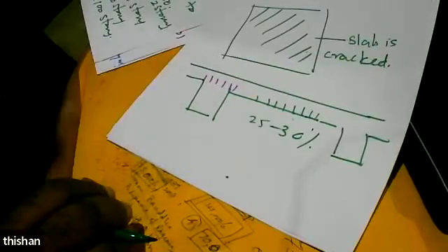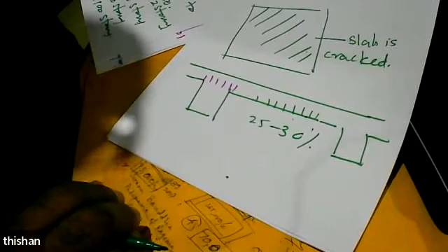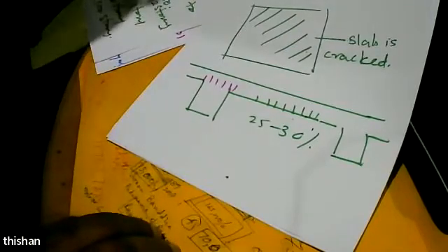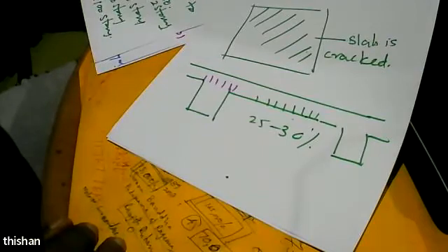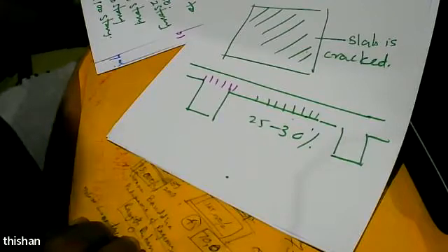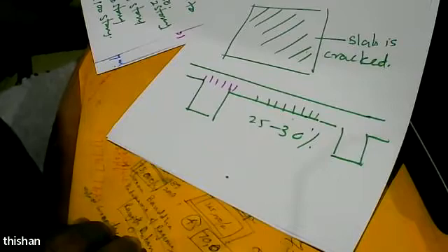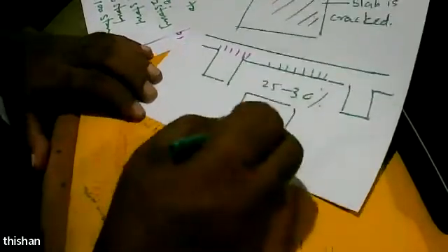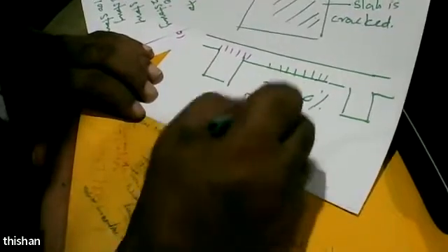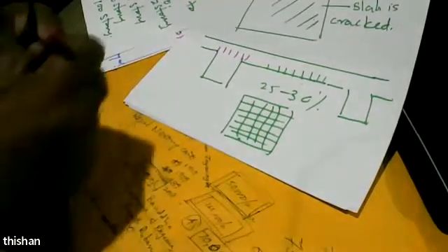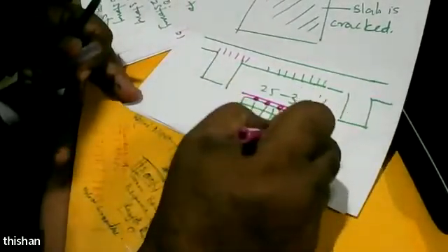So what you do is you go to set modifiers in the program and then adjust the stiffness of the panel that is used to represent the slab. So basically what you do is, now when you're modeling, you have two options. I'll do a small diagram. One option is break it into this. And then say that they are all connected to these ones. Those are the primary and secondary beams.